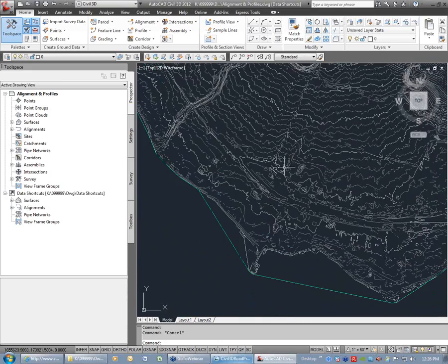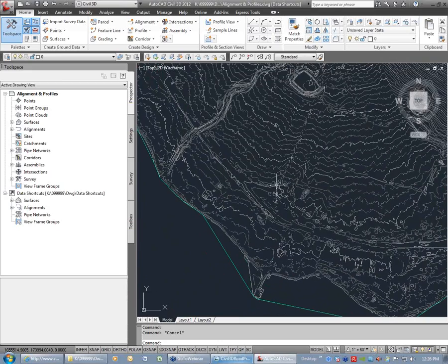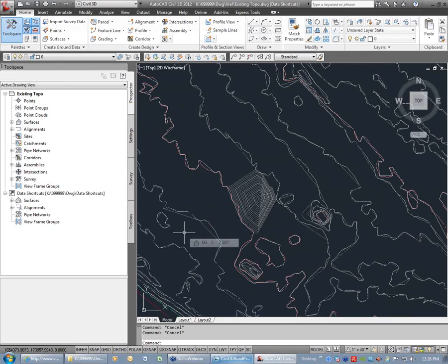Okay. And you'll notice here that nothing's changed. The whole reason for this is just like in an X reference, I have to go back and actually save the drawing before anything updates. It's basically like a save and then a reload like an X reference. With a data shortcut, they call it save, and then it's synchronize is what they call it. So I just made a ridiculous edit to the surface. Wherever that thing is referenced, I just saved it now.